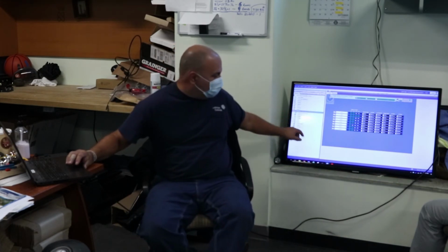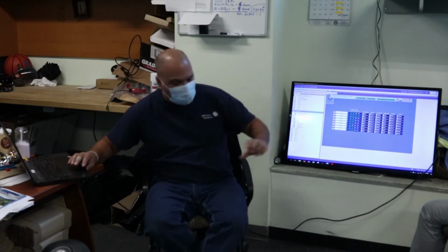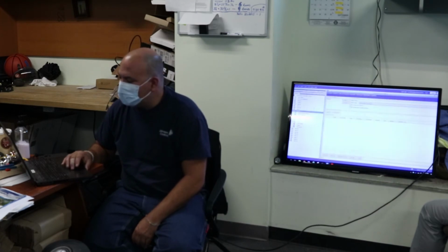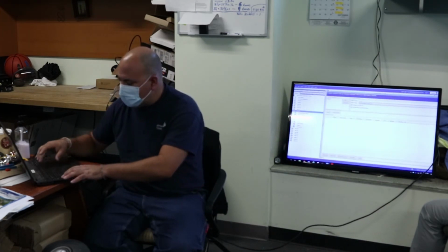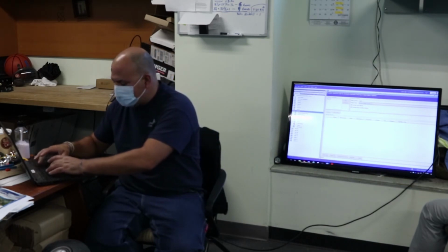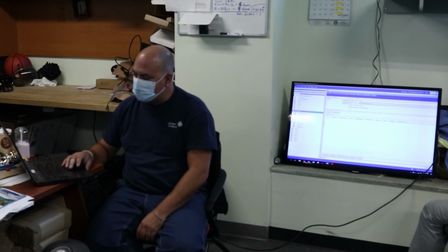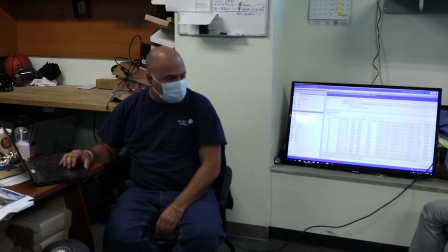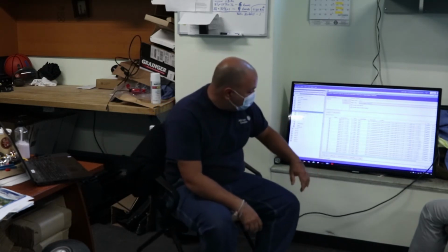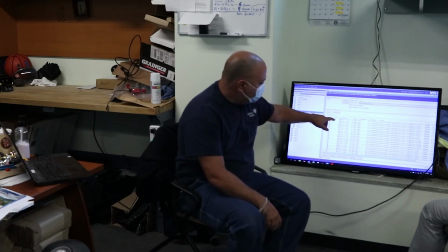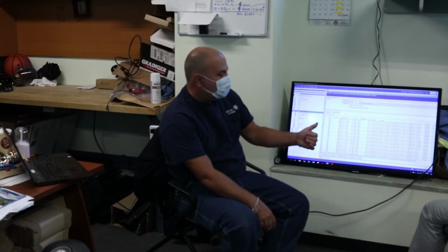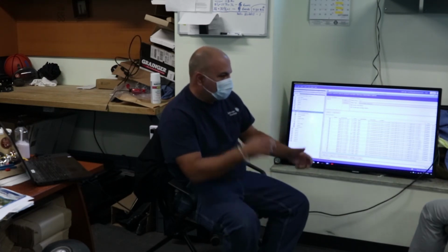Okay, I'm going to highlight, and you could highlight anything and limit it to whatever you want to highlight. Well, let's start with the NAE, and I wanted to do a global search, okay? So if I put an asterisk in front, that eliminates any headings before it, and I want to see the zone temperatures. So ZNT, I could do a search, and this will bring up all the zone temperatures for that associated AHU. All the VAVs are tagged by what air handler they are, what floor they are, and then the number of the VAV on the floor.